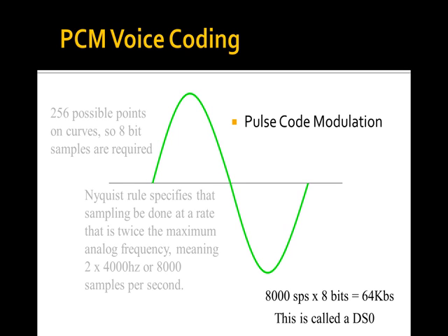Now, there's a very smart fella named Nyquist, and he got to looking at this whole idea of sampling. He actually did this in the 30s, before anybody could even really do it. He came up with a rule, of course, the Nyquist rule, that to unambiguously sample an analog waveform, in other words, to come up with a set of samples over time that only describe one waveform, you have to sample the input audio at a minimum of twice the highest frequency that's going to come through that system. Okay?